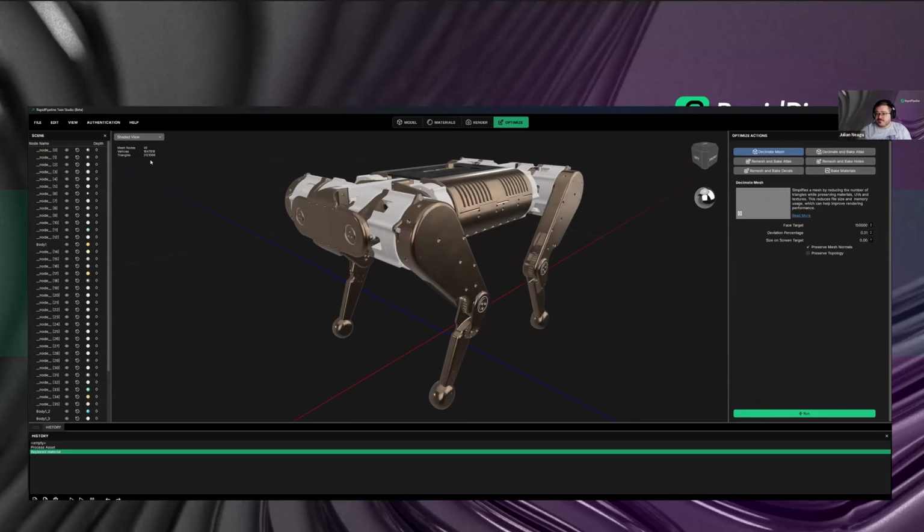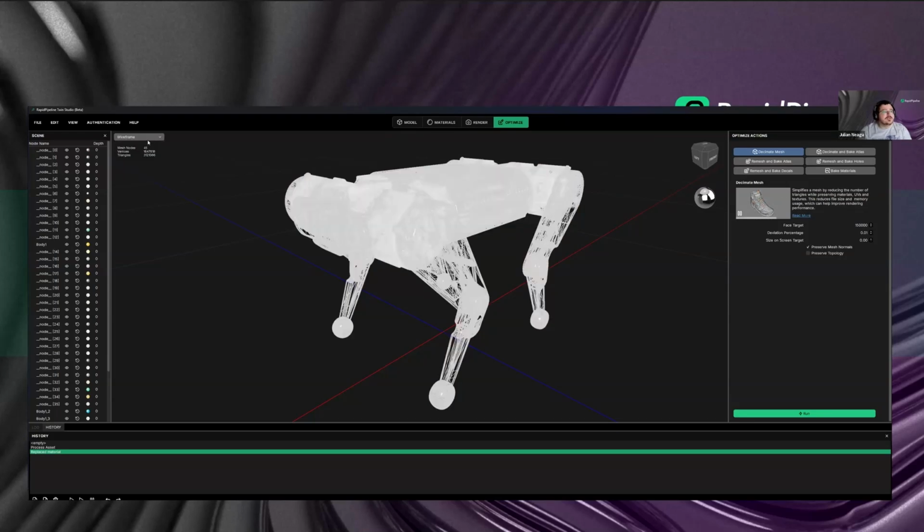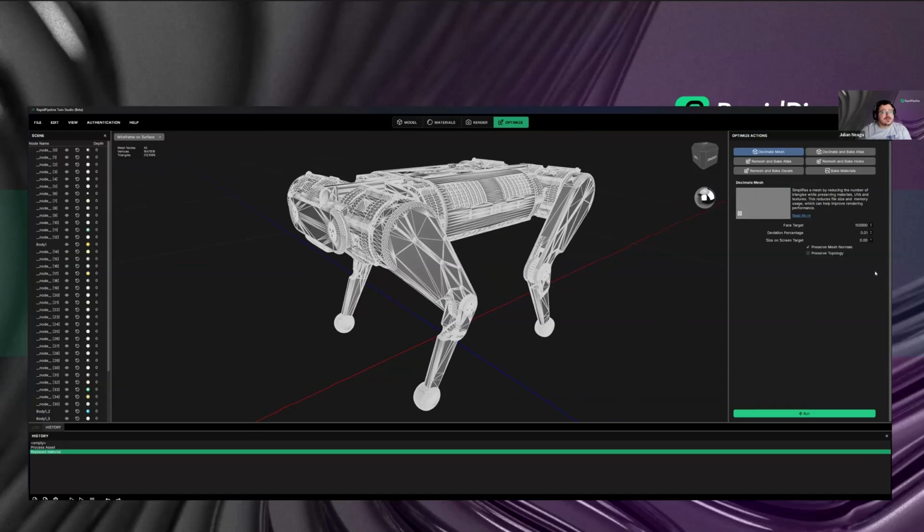But yeah, so just to demo a little bit, we have right now, I think, 3 million triangles resolution. So I can show this a little bit on the wireframe, on surface as well. And on the decimation side, let's try here to go maybe to something like 800K or so. It could also be less or more. We also have a deviation percentage here, which is cool, which automatically decides the error between the input and output surfaces. So you can actually use that for batching over a larger database of files, and it will give a smaller resolution to simple shapes, like say a pillow or something, and then it will give a higher resolution automatically towards like a CAD assembly or something, which is more complicated.